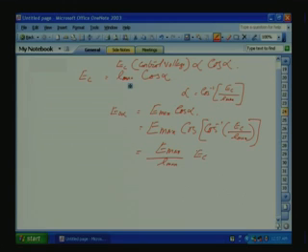So, here if you vary EC proportional to cos alpha, our output voltage, since this is constant, will be proportional to EC. This is always constant, the output maximum. So, this will be equal to some constant K2 into EC. So, output will be proportional to EC. This is called cosine control.